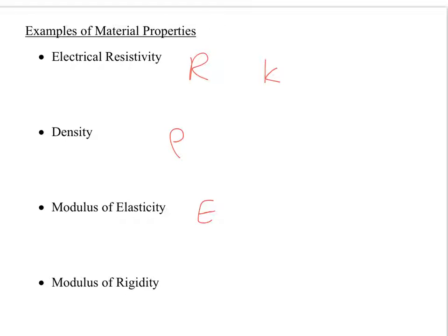Have you ever taken a rubber band and stretched it too much? What happens in the very middle? What do you see happen physically? Yeah, it starts to get really frayed and thin. It starts to vibrate for a little bit. You'll see the very middle of it start to get really narrow. It's a phenomenon called necking, where you pull on something enough, and in the middle of it the material starts to permanently deform.